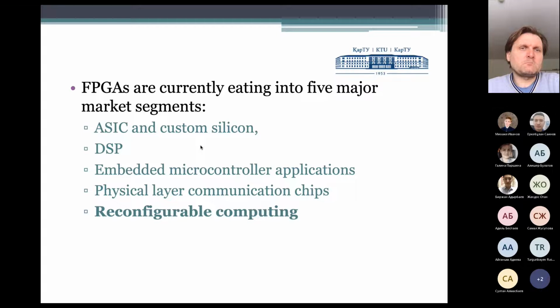And in recent years, we very often use FPGAs for reconfigurable computing. Let's assume we have a very complex spreadsheet, for example Excel, and every function is the same: a set of a few multiplication and some additive cells and some other operations, and we may block them. We may put that operation in a block as one function. When we connect a microprocessor and an FPGA, it's possible to realize that specific function on the gate register structure, and the result will be faster than the result computed by the microcontroller.